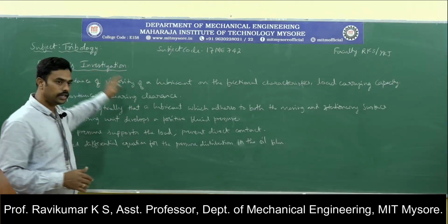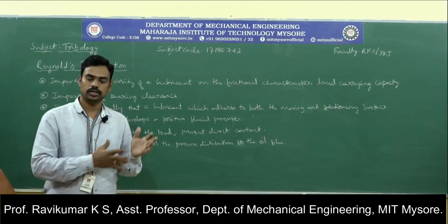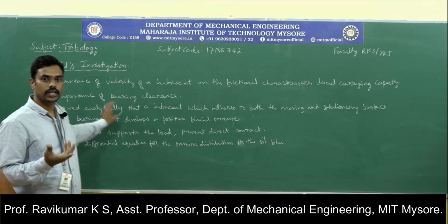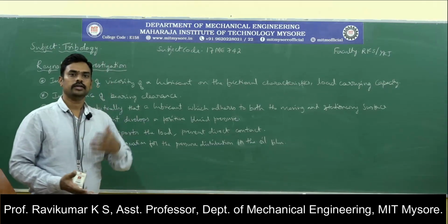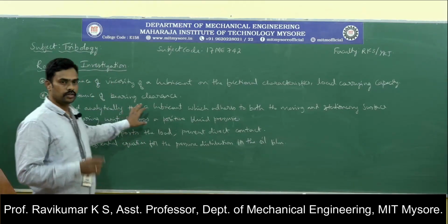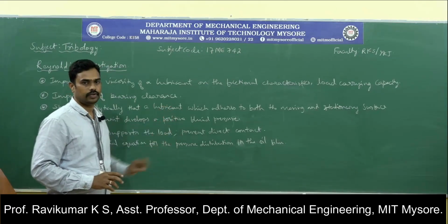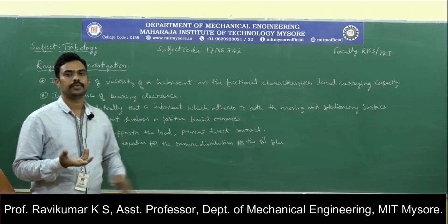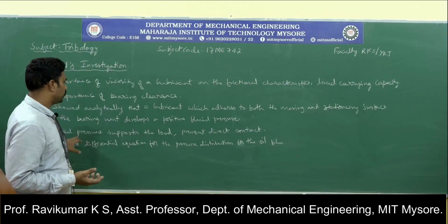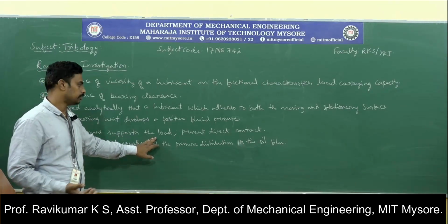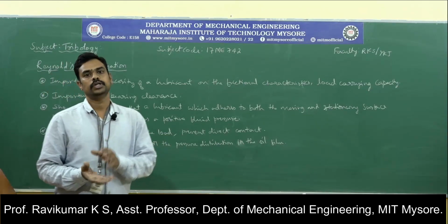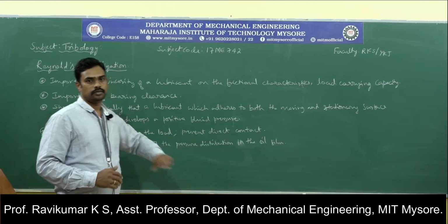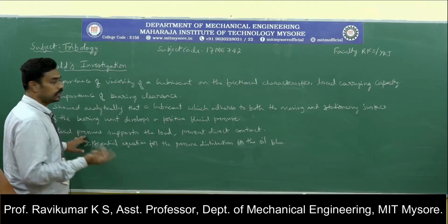But Reynolds continued the study, and he gave some analytical equation to justify the pressure distribution in the gap between the journal and the bearing in the oil film. That is the investigation of Reynolds. Again, the fluid pressure developed in the oil film can withstand the load, can sustain some amount of load, and it can help to prevent direct contact between the journal and the bearing. This is one of the observations of Reynolds.